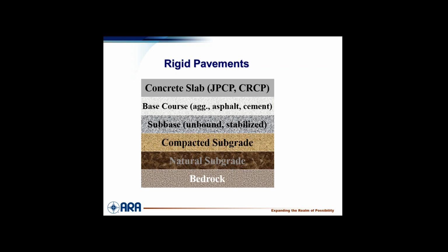In asphalt pavement design, you always assume complete full friction and bonding. There's no slippage in there. You'd be considered an absolute fool if you design an asphalt pavement and put a slippage plane in there. Although sometimes that happens in the field if the contractor doesn't put a tack coat down or waits until it's cooled, the asphalt is cold and tries to bond them together.